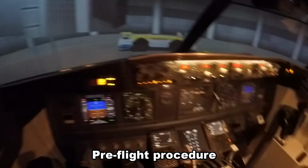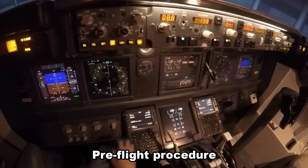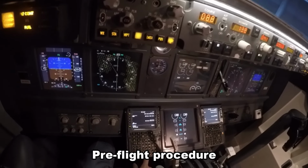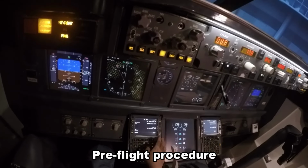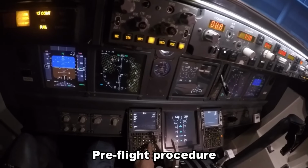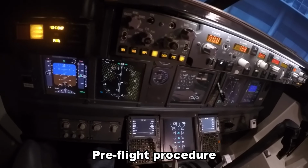Alright, and then we'll just program our CDU. So we'll just go into menu, index, ident. So the ident page is correct. We'll just go to pos init, and we're not in YSSY, we're in VHHH, which is Chek Lap Kok Airport. We'll just set our IRS position. And we'll be taking off from runway 25 right and landing back again at Hong Kong, Chek Lap Kok Airport on runway 25 right. We'll just activate that. And we'll just go to a perf init.